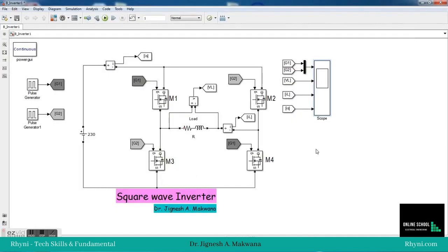So this is a simple square wave inverter, very useful for very low cost applications where only a resistive load is there, or a lamp, bulb or light. But it is not suitable for running CPUs, desktops or fans, as harmonics will be there. This is the starting point from where we can understand the operation of an inverter converting DC to AC in single phase.